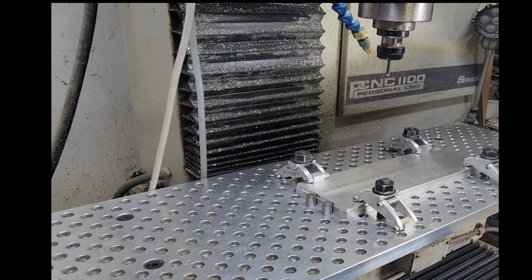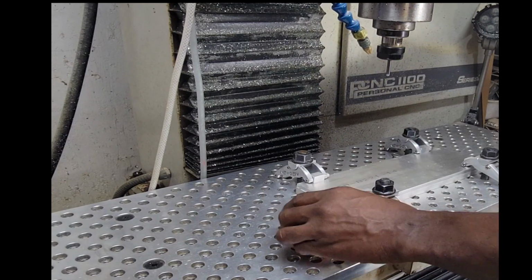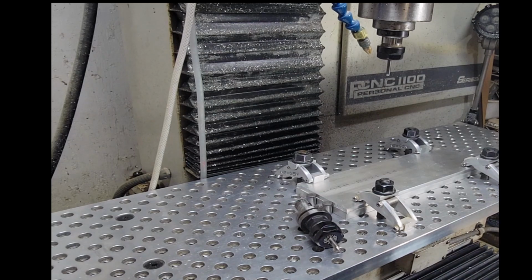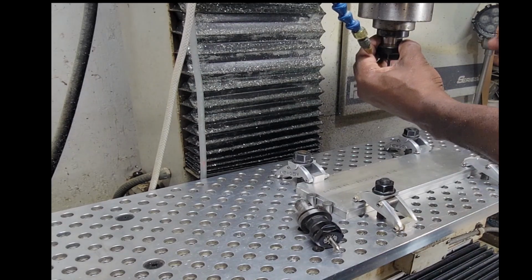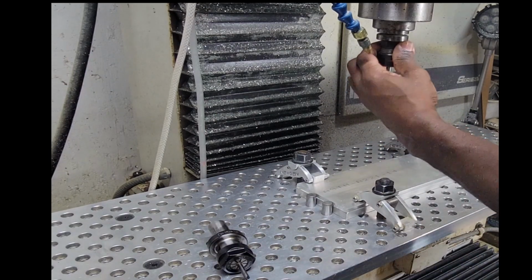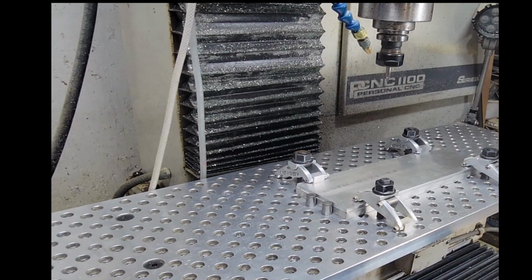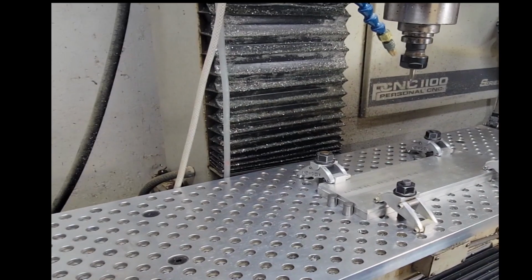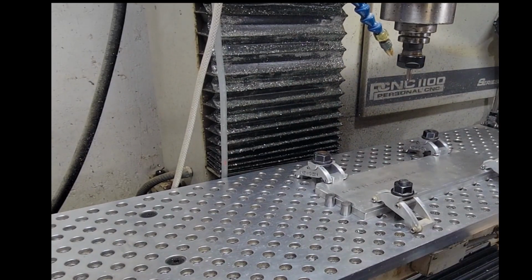So I'm going to load up tool number 1. And at the same time, I'm gonna put the offset up maybe 4 inches up on top, and then I'm gonna run tool number 1 just on the air. I'm gonna act like the Z offset is up on top of the part, just to cut the air, just to prove out my program. I'm gonna load tool number 1. Now I'm gonna act like I'm actually cutting the part, but it's just going to cut it up in the air.